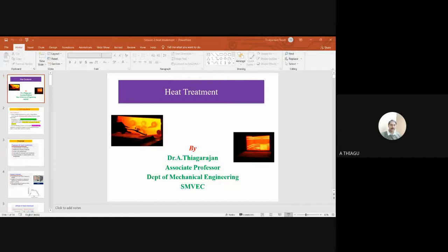Finally, we look at some microstructural modification from the full annealing process or normalizing. Okay. So here you can see the coarse forms of pearlite, but in the normalizing process we can see the lamellae are fine and smooth. That is a major difference. Based upon the modification of the structure, it will create better mechanical properties. So when we speak about the temperature and cooling process, it will change the microstructure. We have to concentrate on the parameters or variables of temperature and composition. That is very, very important.